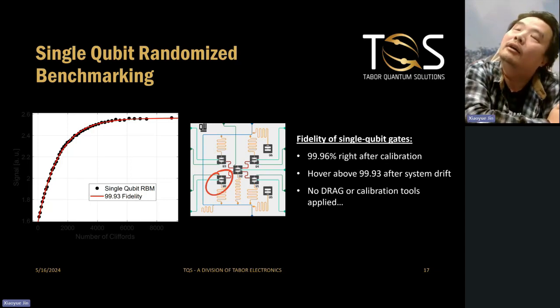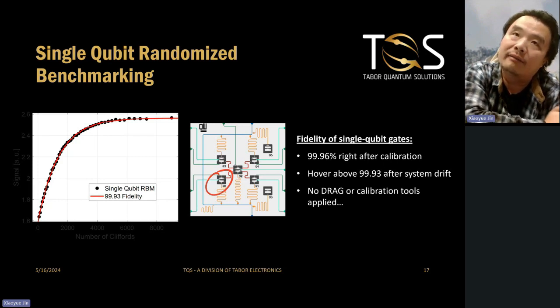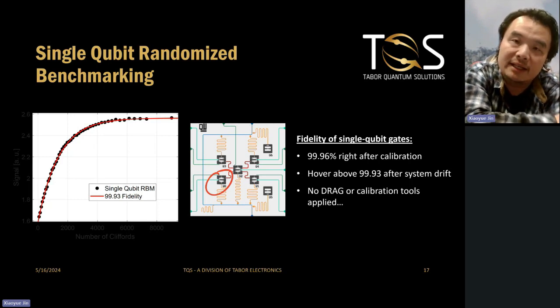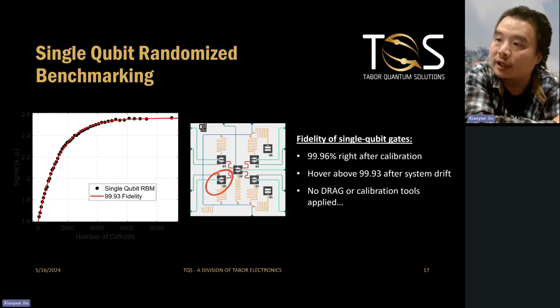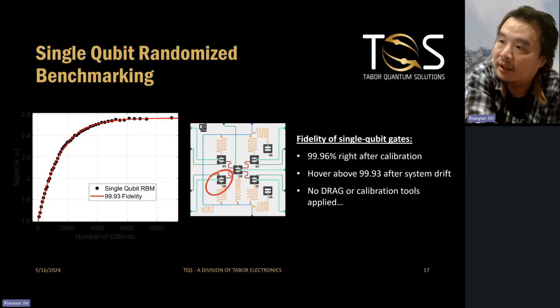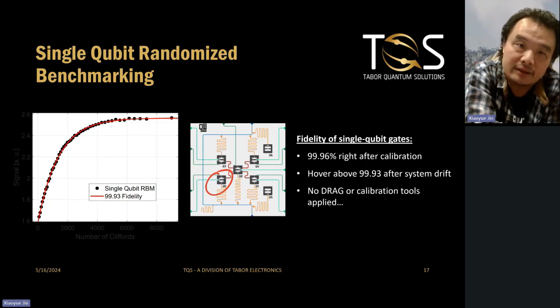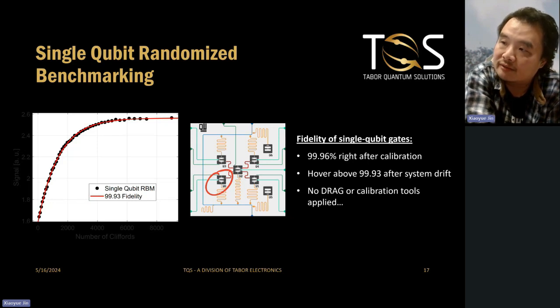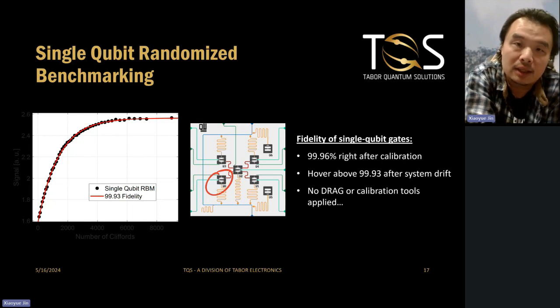Here, I also want to emphasize that when the designer designed the chip, they have this traditional method to move the qubit frequencies around so that they match each other. In that way you can induce the two-qubit interactions and realize a controlled-Z gate, which has been out there for more than 10 years, I believe. And this time, QuantWare reported that they can achieve 99.7% fidelity on that front.